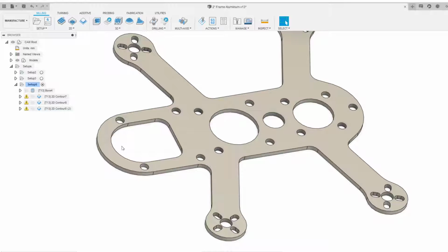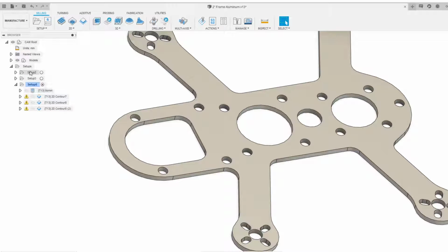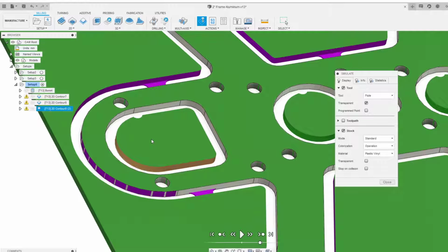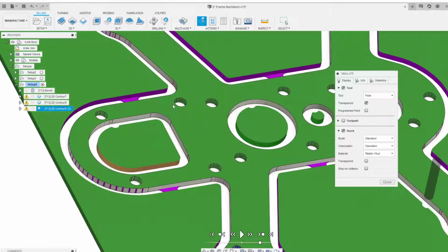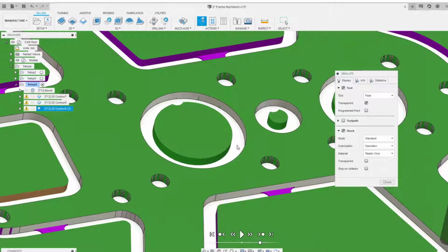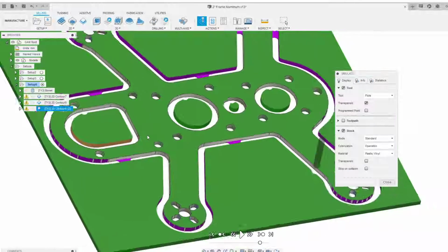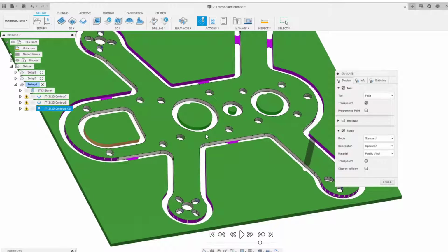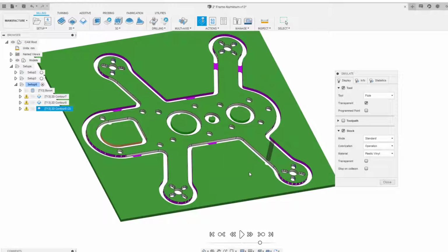If you don't use double-sided tape or something like that, and you want to cut this out kind of the way that I've cut it out here, where we have like this little island in the middle here, I would also add tabs to these as well. So the borer cuts all the material. You might want to use a contour instead of a bore for these interior ones. That way you can add tabs. But if you're just clamping your material and you don't put tabs on here, these things will get loose, and they may or may not stay there. They might fly around. They might crash into the bit and cause some problems with your work. So just some other things to consider.